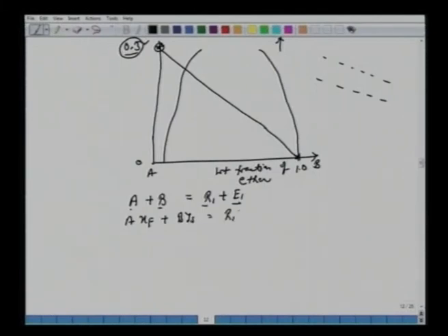So we know these compositions here and here. Here we have plotted X versus X and Y versus weight fraction of ether. So we can solve mathematically, or we can solve graphically. We have 1, 2, 3, 4. These are all known, given to us. X_R and Y are not given to us, but we know they are in equilibrium, right? So 2 unknowns, 2 equations. We have to calculate this xm.